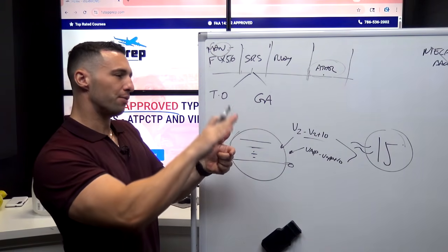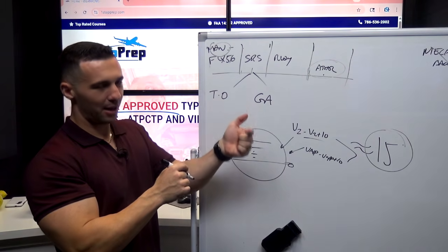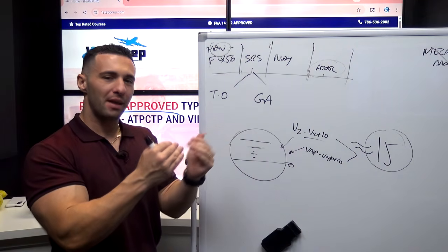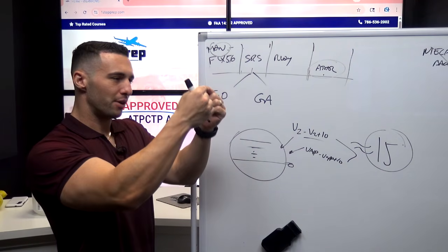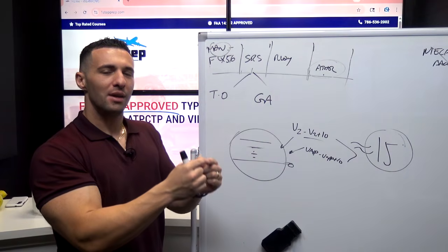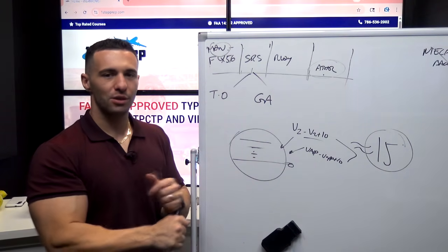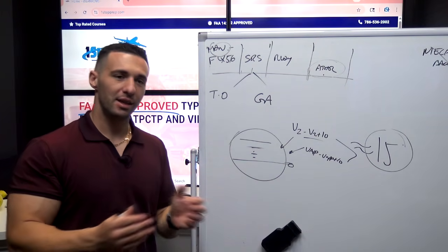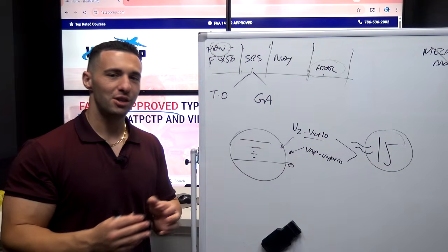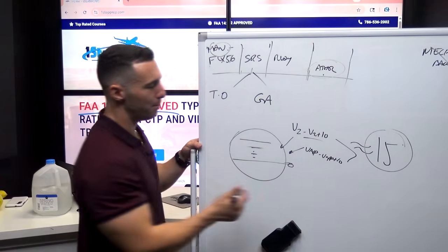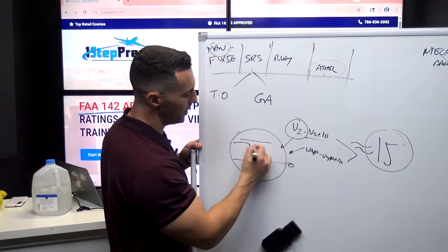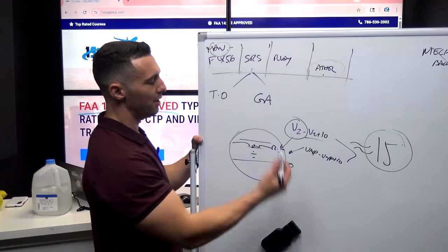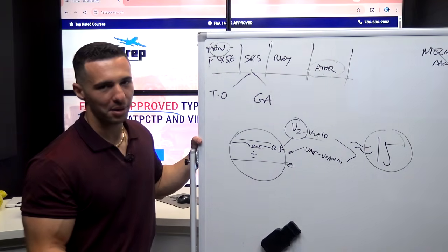You're going to notice if you follow the flight director up, the speed starts to trend back and it bleeds off. And then when it gets right back within that range of V2 to V2 plus 10, the flight director bar starts to come down a little bit more and it meets you back towards that 15-degree mark. Now, that is all done automatically, and that's all true, assuming we're two engines. And then, of course, if we're single engine, then it's mainly pitching for V2, which is roughly 12.5 degrees nose high. It's not targeting that per se, but it's targeting a speed, and it's going to happen to fall in line with basically that pitch attitude.